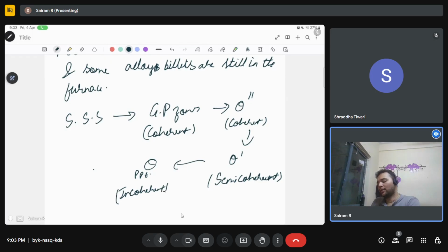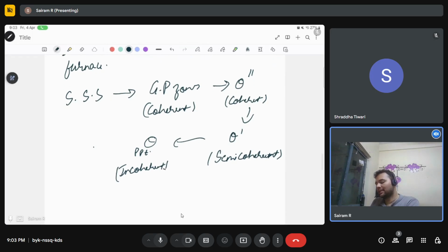There is a slight decrease after the solid solution strengthening, because with increasing precipitation, copper is moving out of the solid solution, and then the GP zones form, which are coherent but are precipitates anyway, then the theta prime forms, then theta forms. So the maximum hardness is somewhere between theta prime and theta double prime. We have the max hardness.